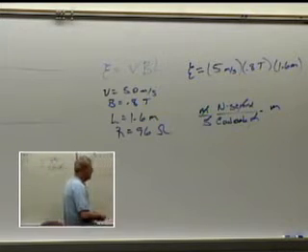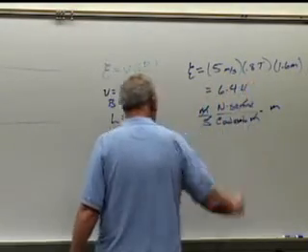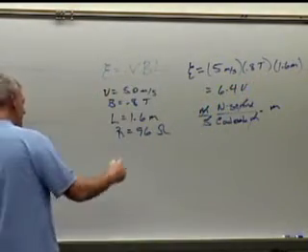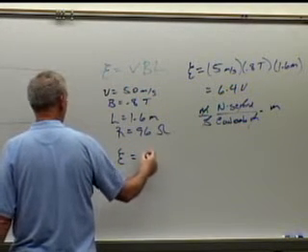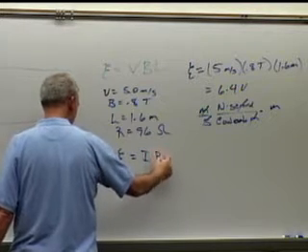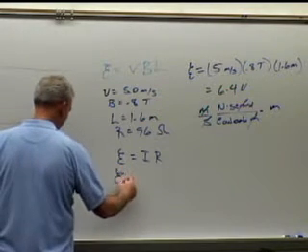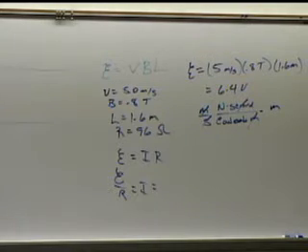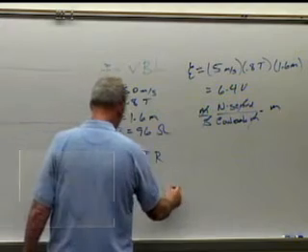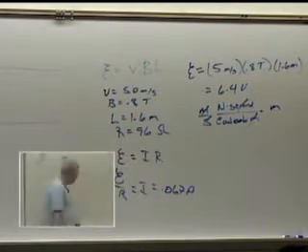What would be the amperage through this thing? If we wound up that this is 6.4 volts, what would be the amperage, I? You can do this. You can do E, the electromotive force, equals IR. So you know R, so you can figure out I. It's just Ohm's law again. And that comes out to be like 0.067 amps. This is a nice little problem because it covers everything. So we found the amperage.